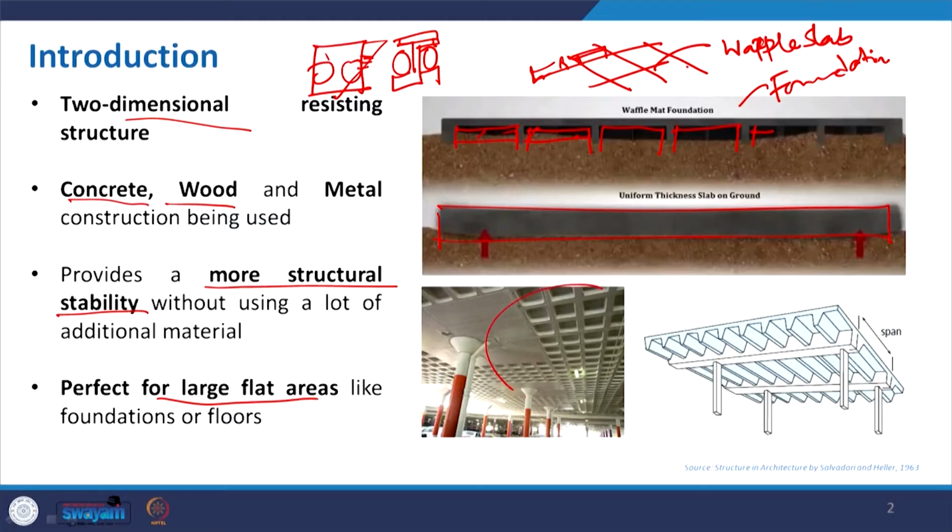We can go for a cell structure, we can go for a dome structure, but if we confine ourselves to a very straightforward flat structure, then this waffle slab or grid structure can help us, where cross beams in both directions can help increase the span required for, say, a ballroom, a party room, or maybe a conference hall, etc. So, here you can see another picture of the same thing, where the large span is being supported,